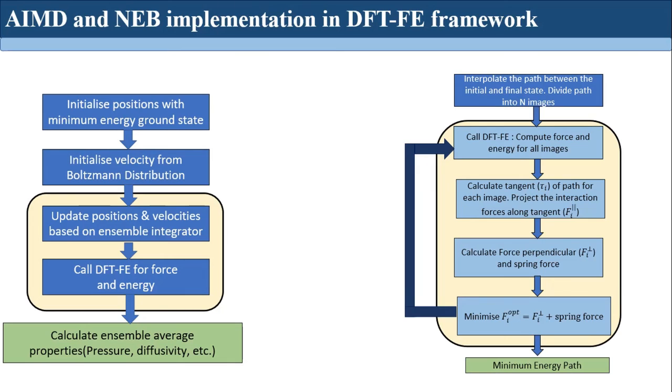So the advantage which finite elements will provide is, first of all, it can handle adaptive meshes, which allows better computational efficiency. And also you will have better scalability, because usually to get the chemical accuracies which are required in finite differences, you usually have to have very high order stencils, which affects the scalability. So finite elements have been shown to be much more scalable than finite differences.